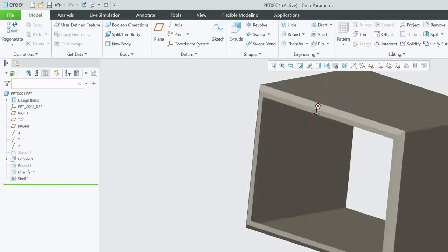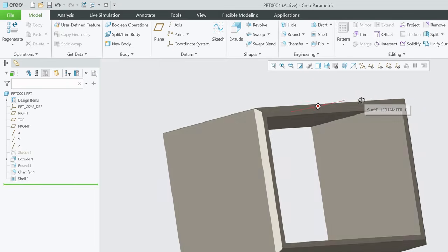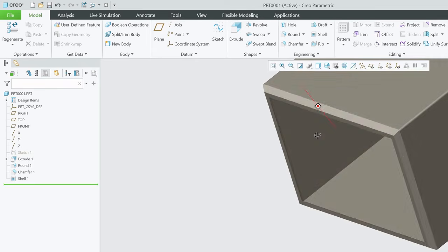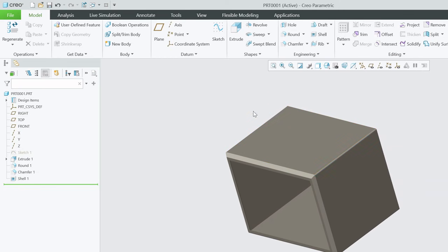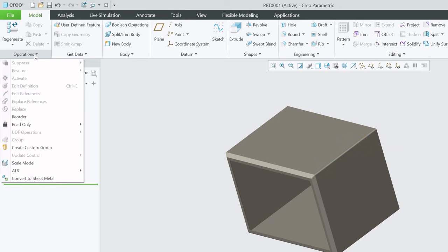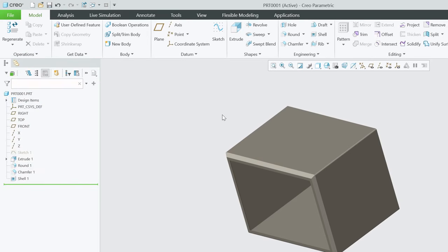See? Simple, easy. If you're doing sheet metal and so on, this is quite an easy way to create boxes and so on. Then you just convert to sheet metal, which is on this drop down right here. Convert to sheet metal. Then you can add your tears, your bends. I mean, if you're going to do that, you don't need rounds. You take your rounds out.